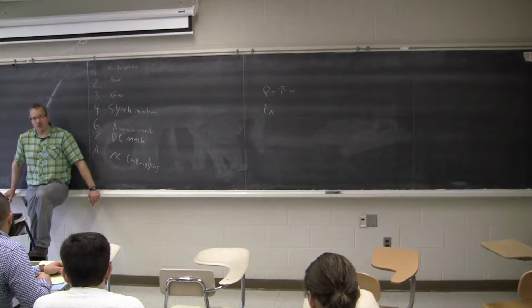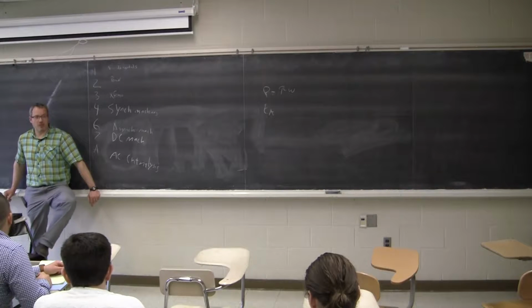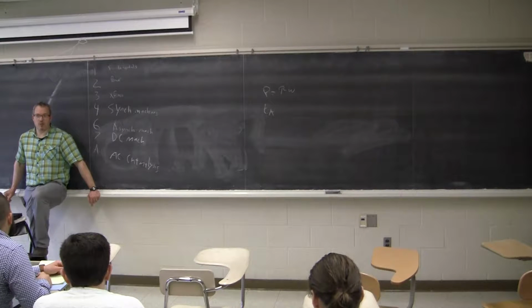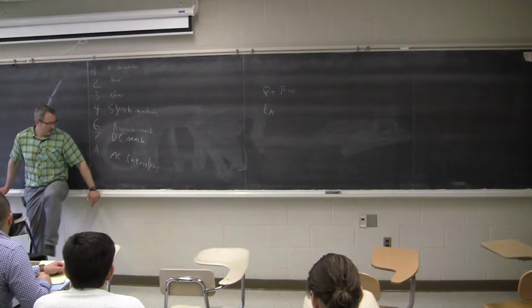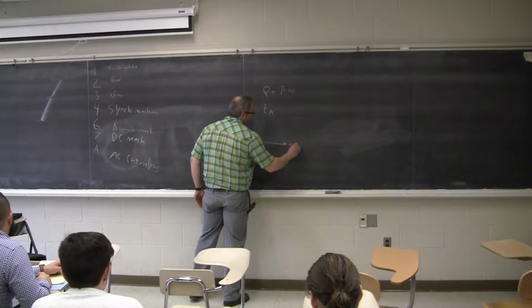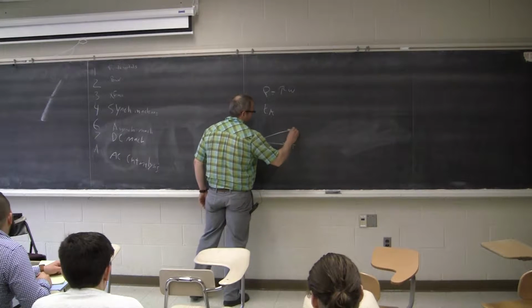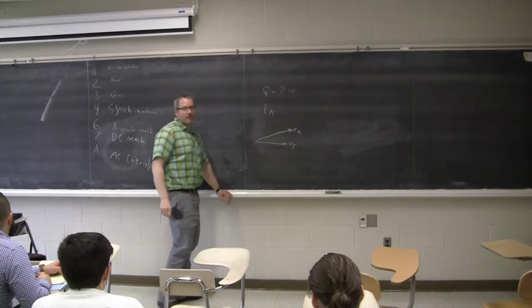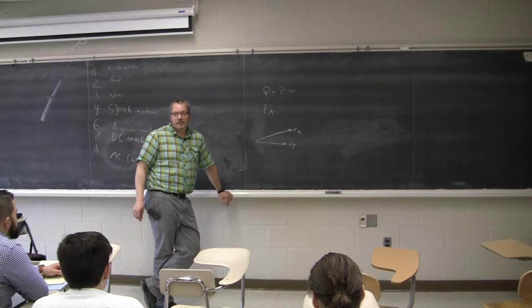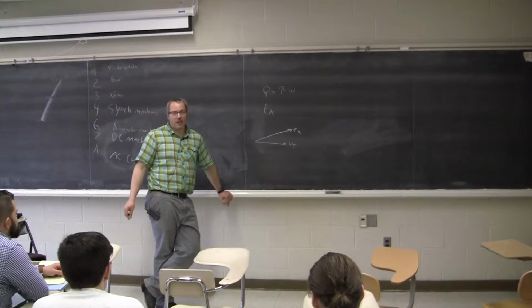We also looked at voltages. We could tell the output of a synchronous machine, whether it was a motor or a generator, just by the angle delta, which is between EA and VT. Remember, is this an impedance diagram or a phasor diagram? It's a phasor, because those are voltages, sinusoidally varying constantly.